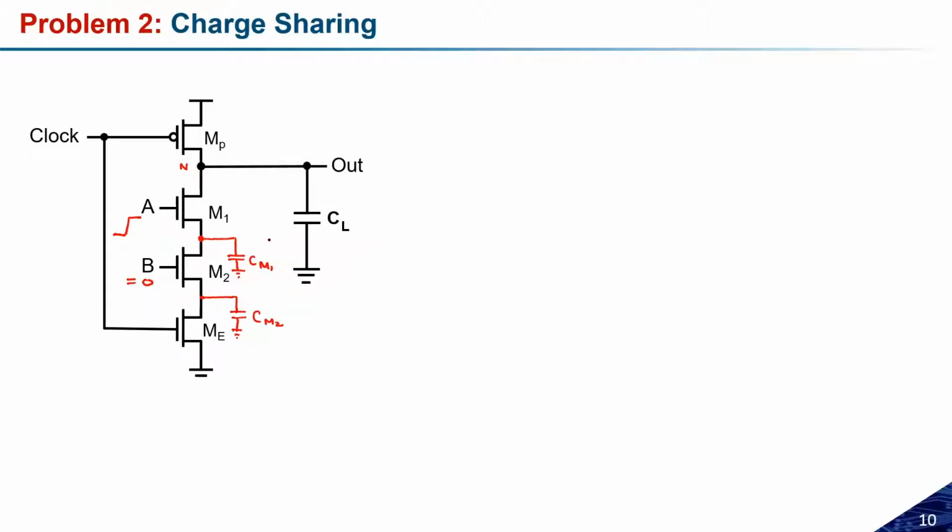Even though the circuit is in the pre-charge mode, with no evaluation mode, if there is some transition in one of the inputs, then the charge stored at the load will be redistributed. Definitely it will get some path, because transistor M1 is in the on state.